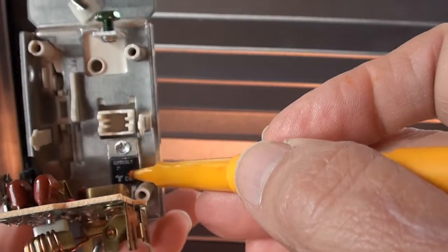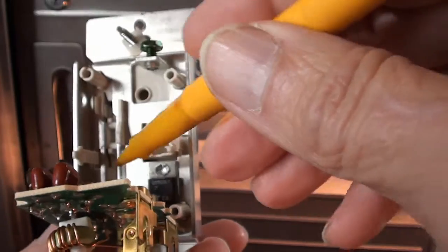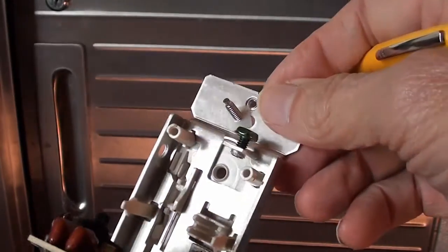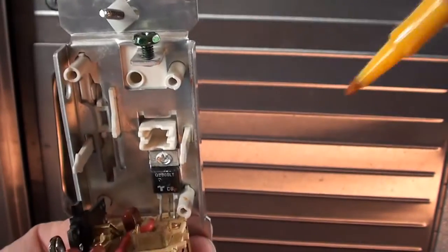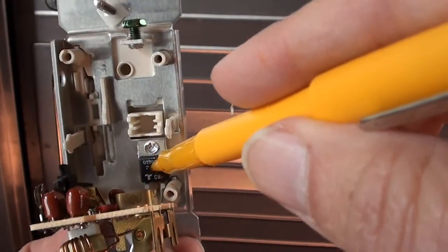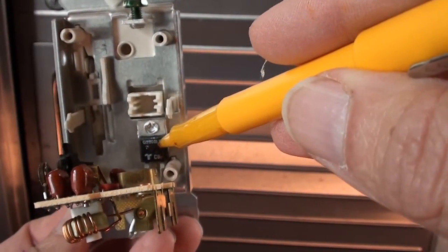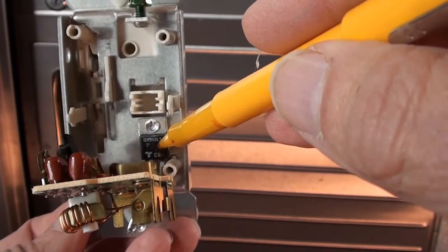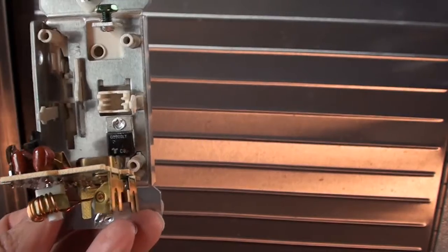This will generate some heat, so it's always mounted on a metal heat sink, and that's why these things always have this chassis around them to dissipate some of that heat. But essentially what's happening is this device turns the power on and off on every cycle. So this thing switches 120 times a second, and we'll look at that waveform now.